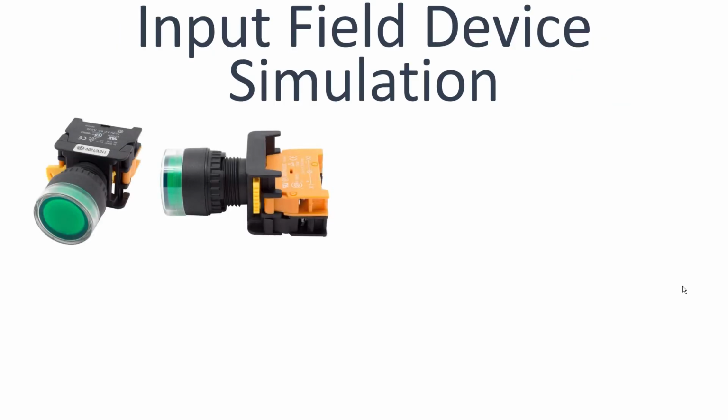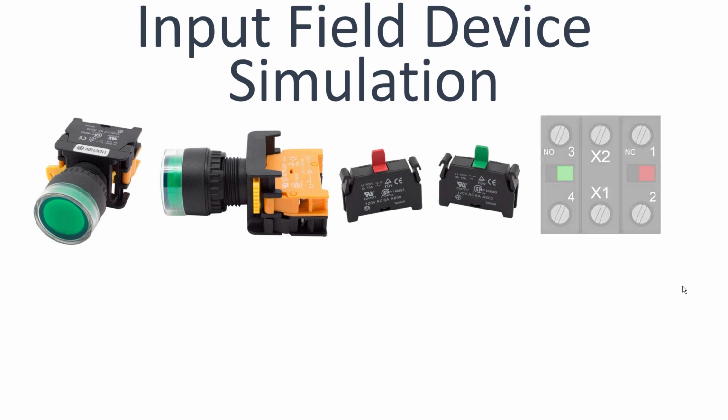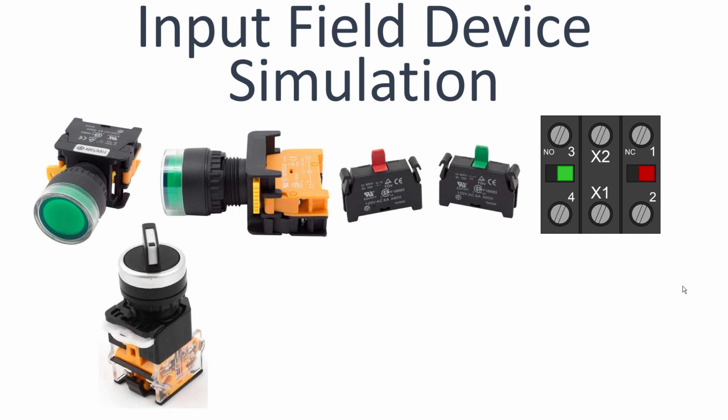Okay, input field devices. Now these are the large push buttons with LEDs in them. And if you're going to use something like this, you're going to need a larger box. But these are very inexpensive. Selector switch is the same thing as a toggle switch. There's different kinds of toggle switches. Center off, spring return to center, single pole, single throw, single pole, double throw, and so on and so on. So this, we'll just say this is a 2-position selector switch. Same thing as the toggle switches. I typically use toggle switches.